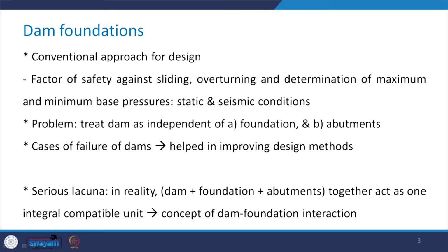As far as the analysis and design of these dam foundations are concerned, most of the time one goes for the conventional approach, where we find out the factor of safety against sliding, overturning, and then we determine the maximum and minimum base pressures under static as well as seismic conditions.